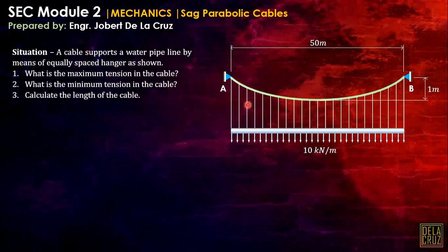So here, the usual questions are: calculate the maximum tension in the cable, the minimum tension in the cable, then calculate the length of the cable. These are the questions usually asked here. So how can we calculate the maximum and the minimum tension in the cable? This is what you need to remember in problems like this.